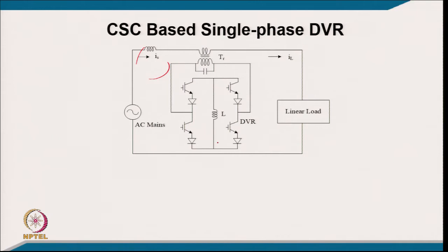So, now this current source converter typically has an inductor as the DC link energy storage. As a switching device, a current source converter requires negative voltage blocking capability, and the transistor family, either MOSFET, IGBT or BJT, does not have negative voltage blocking capability. So we have to connect a series diode in addition to take the reverse voltage block across this. So when it conducts, there is a loss in both the devices.